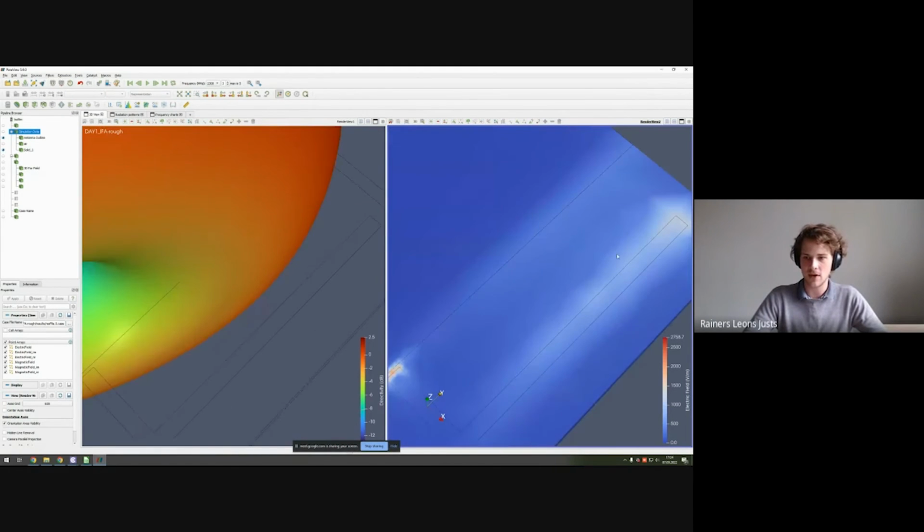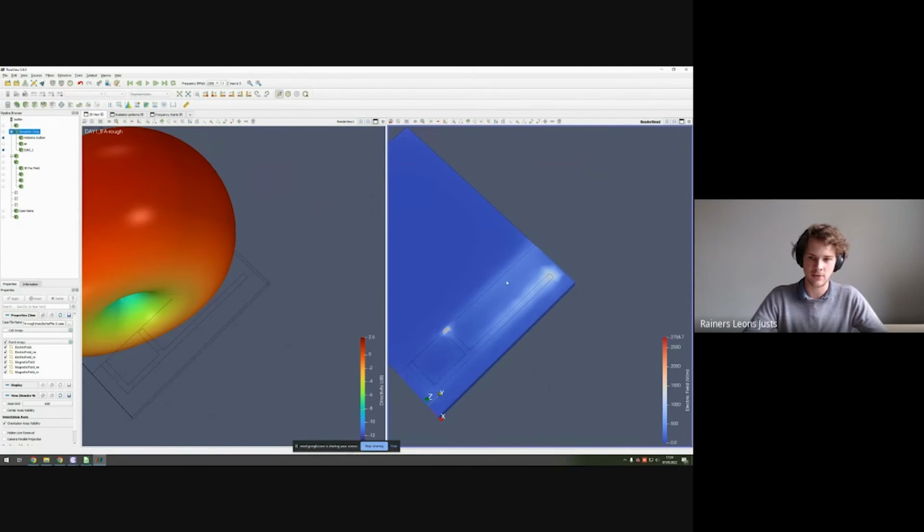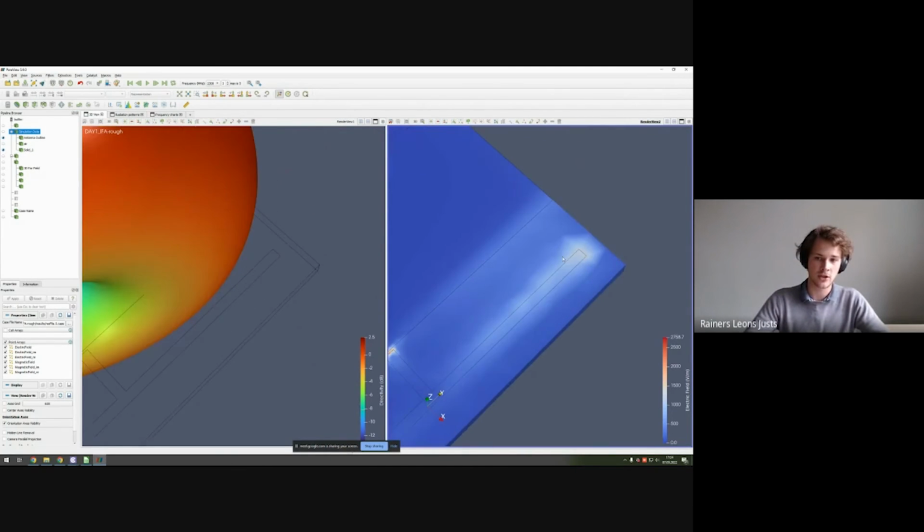As you can see, we have these large, rough, jagged edges in the E-field distribution. This is generally not a good thing because you're losing some resolution in your calculation. To validate how finely you should be meshing your model, or in case the automatic mesher has not done a good enough job, you can take a look in here and see these jagged edges.